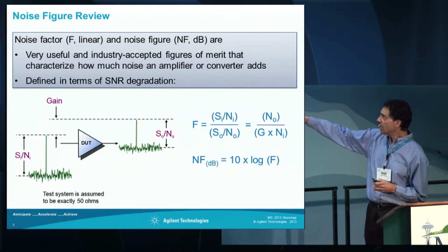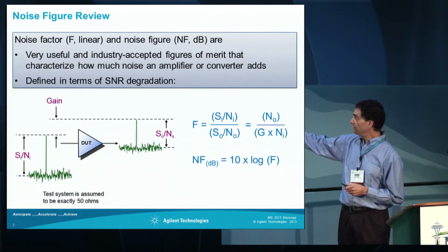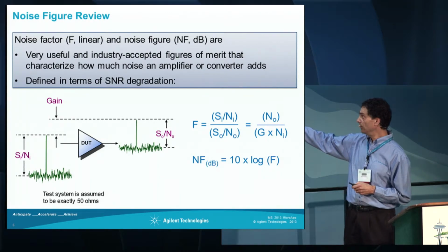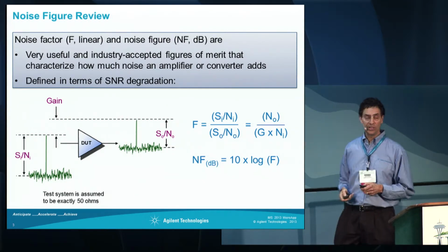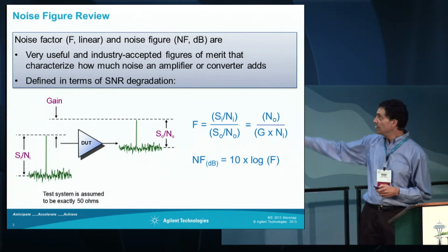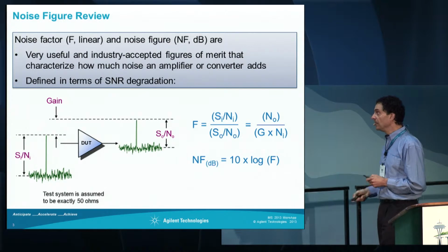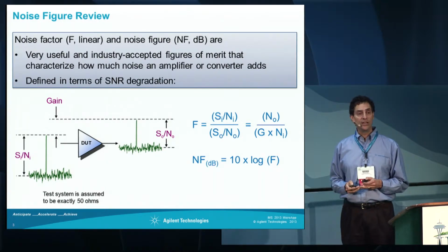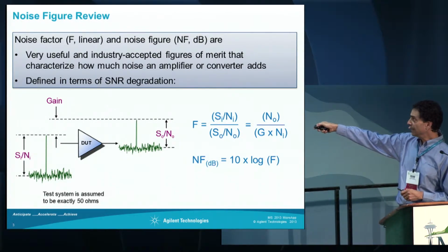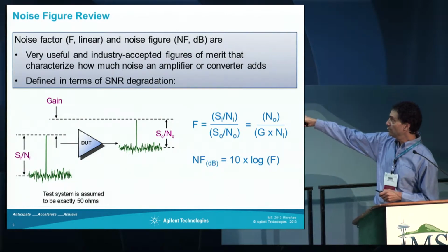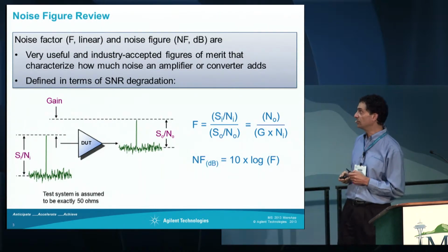It can mathematically be expressed in this sense, where, if you know the gain of your device and you know what the input is, this is normally KTB, that's how much noise you would expect at the output if it was a perfect device. If you ratio to the actual noise output, that will give you an indication of your noise figure. And this formulation of noise figure helps explain how the PNA-X actually measures noise figure, because we can measure gain using S parameters, and we can measure noise output as a second, completely independent measurement, and calculate noise figure.